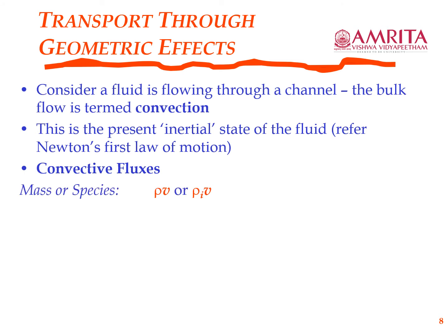For mass, it is rho into V. That is basically kg per unit area, say meter square, per unit time, which is second. So this is kg per meter square per second, and that is simply given by kg per meter cube, which is your density, multiplied by meter per second, which is your velocity. So rho v is mass flux. You have studied this in